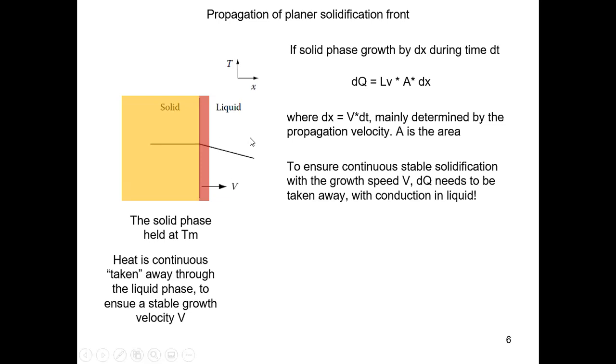And in our system, we'll use conduction because there may be some radiation as well, but the main mechanism is conduction, because we definitely don't want to stir the liquid during the solidification; if you stir the liquid, you're going to create a disaster of the microstructure. So we just wait a little longer for the heat to slowly dissipate through conduction. Okay, but if you take any heat transfer class and we're talking about heat conduction, you realize that the mathematical relation between the heat flux and the temperature gradient is exactly the analog of Fick's first law, right?